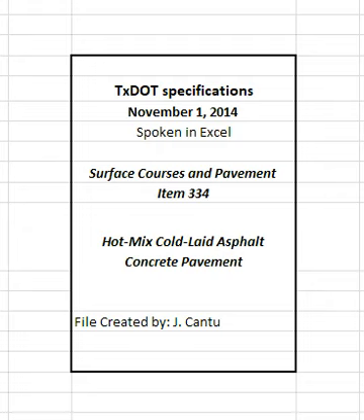2.5 Tack coat. Furnish CSS1H, SS1H, or a performance-graded, PG, binder with a minimum high-temperature grade of PG58 for tack coat in accordance with Item 300, Asphalts, Oils, and Emulsions. Specialized or preferred tack coat materials may be allowed or required when shown on the plans. Do not dilute emulsified asphalts at the terminal, in the field, or at any other location before use. The department may sample the tack coat to verify specification compliance.